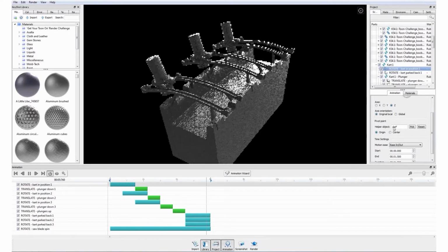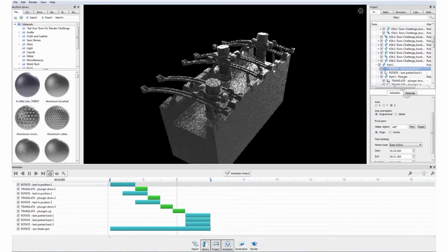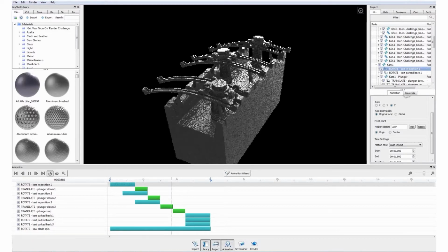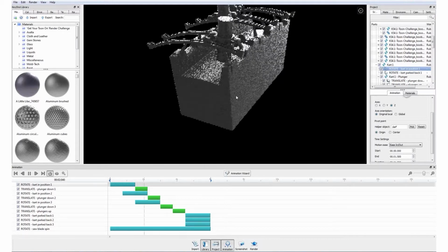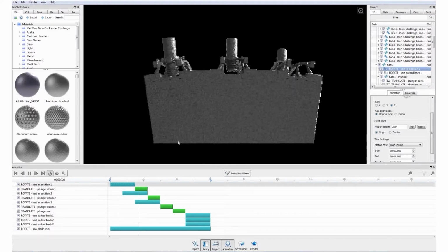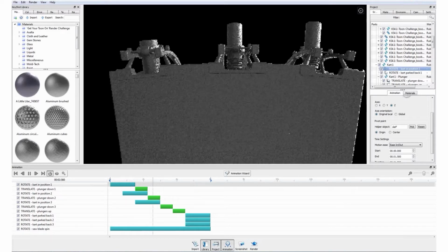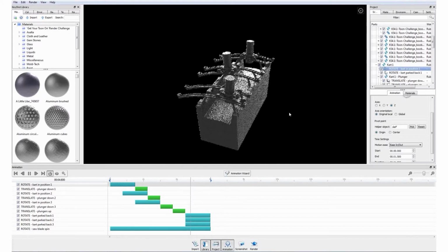So this makes setting up the animation in KeyShot much simpler, because if I wouldn't have put the origin in the correct place while modeling, I would have needed 3 separate helper objects as pivot points, because as you can see, my track is curved, so I would need 3 separate pivot points to get the whole thing animated like it should.